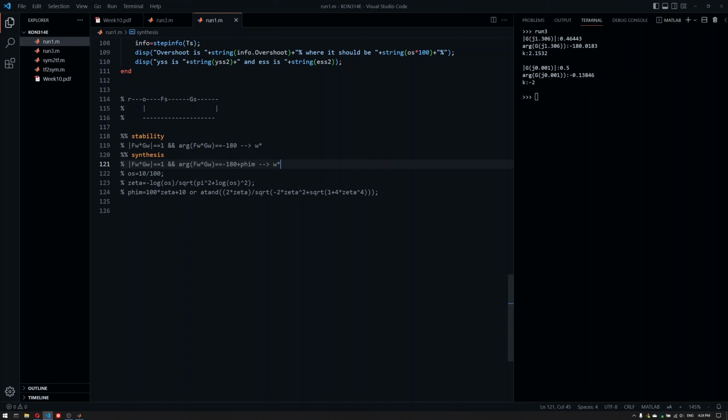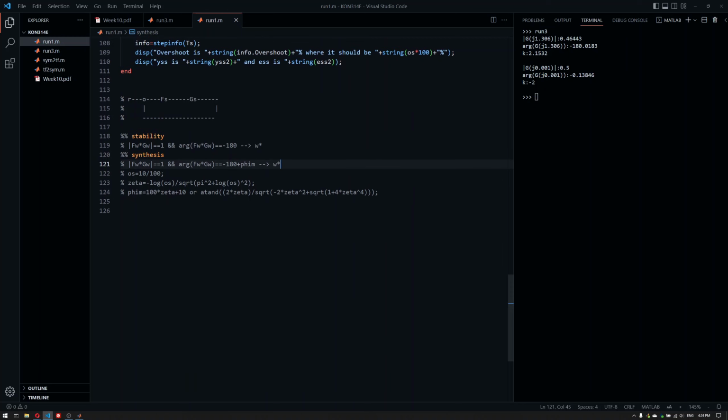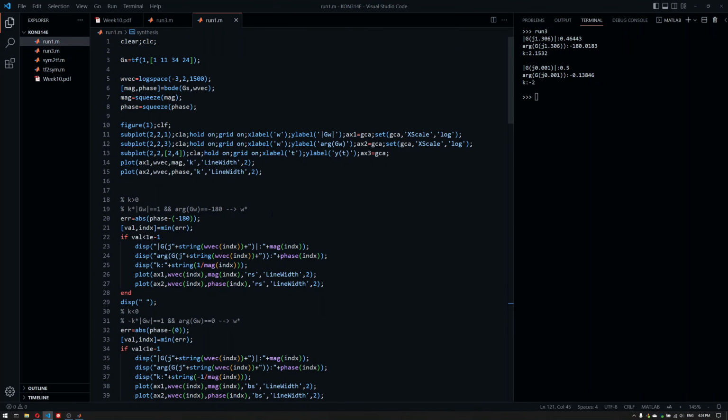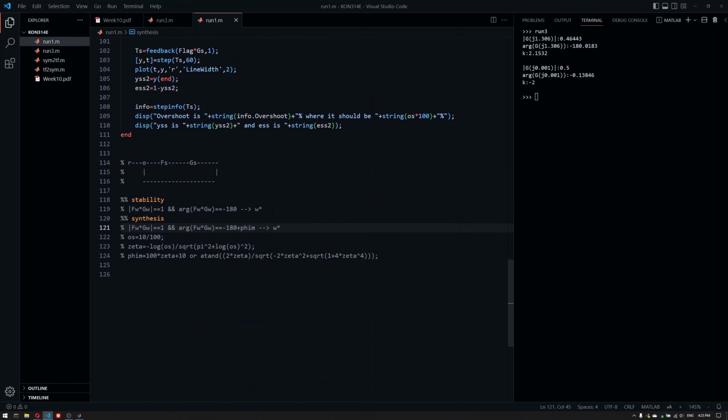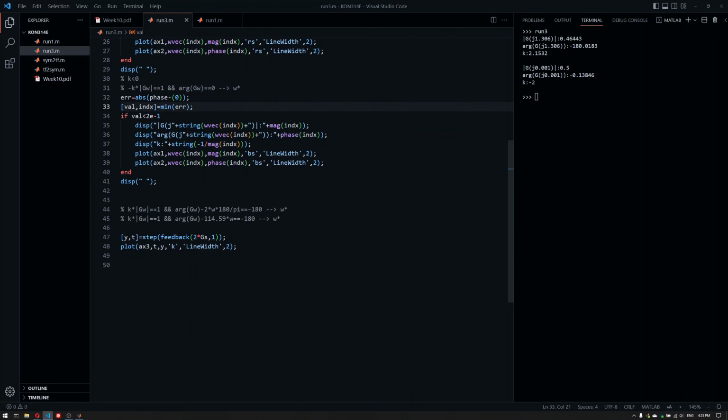If your system has lag or delay in it, and if you have MATLAB, or if you can generate the Bode plot as you wish, you might go ahead and do that. If not, you might have to adjust your Bode plot. Maybe just change the values of the y-axis of your gain plot or phase plot accordingly, or you might end up at a point where you have to use this kind of approach to guess the omega value as exactly as possible.